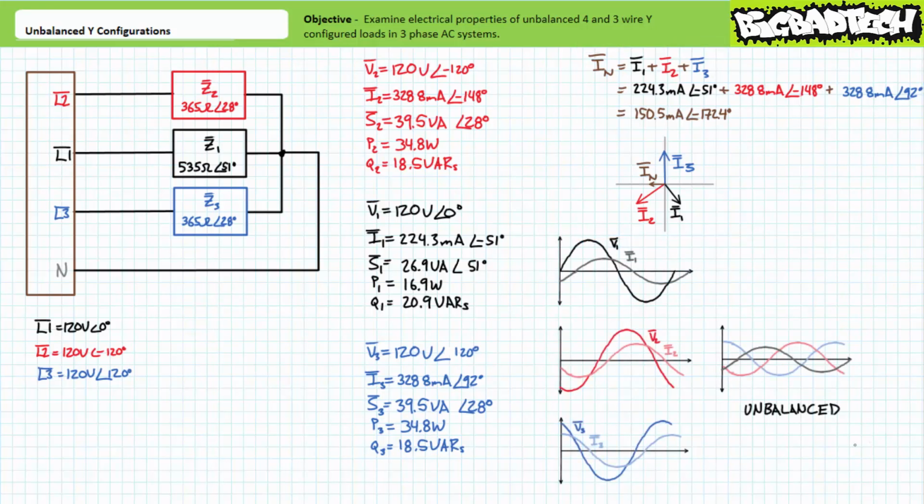If this visualization doesn't do the trick, it may be helpful to remind ourselves what a phasor really represents. You recall, phasor equivalents are simply shorthand representations for time-variant sinusoidal equivalents. Plotted as a function of time, sinusoidal voltage across and current through impedance element Z1 would look something like this. Assuming L1 is our reference, current through Z1 lags the voltage across it by a relative 51 degrees.